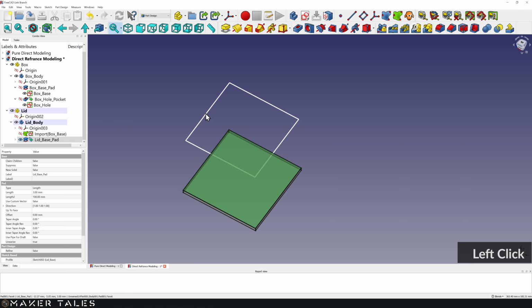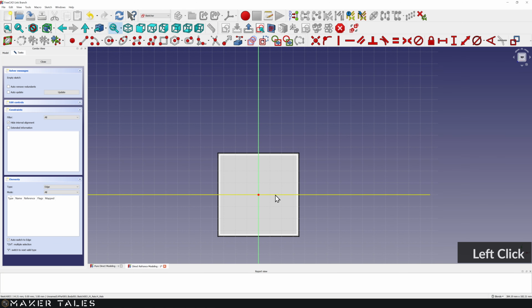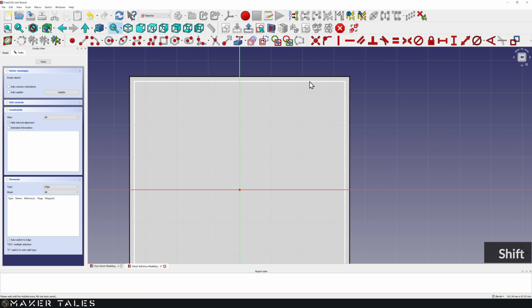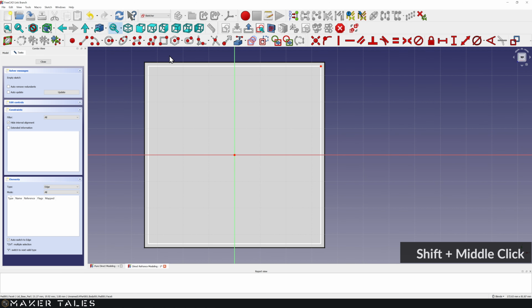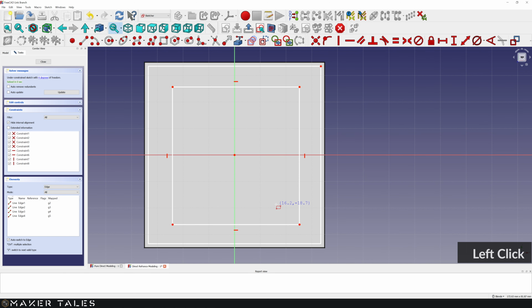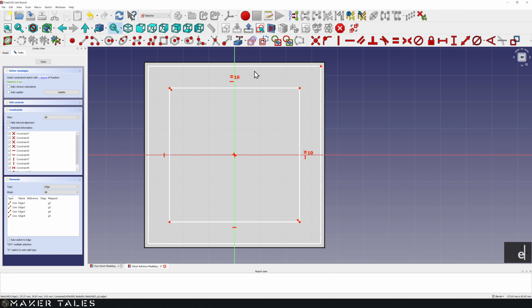Let's select the top face once again, create our sketch, and we already have sort of the outline of where we want to have our offset for our lid. Now, I don't need all of it. Again, I just need one little external geometry reference of that lovely little point right there. Now with that done, we sort of know exactly what we're going to be doing. We're going to create another rectangle. We're going to do this whole center locking once again. We will make these two equal. We will create that construction line.